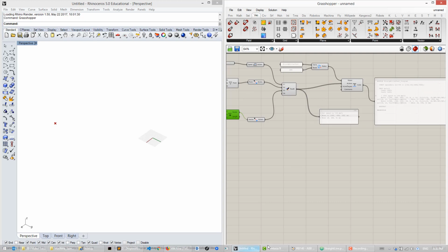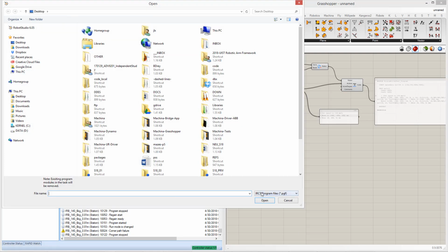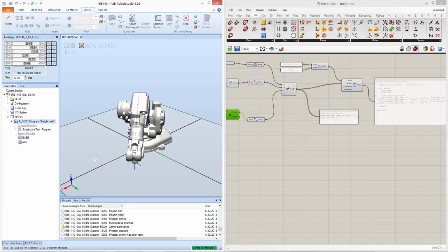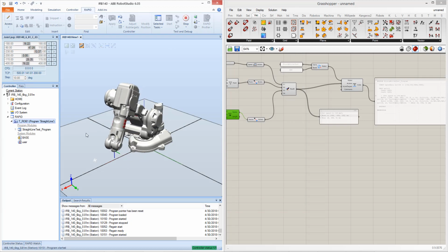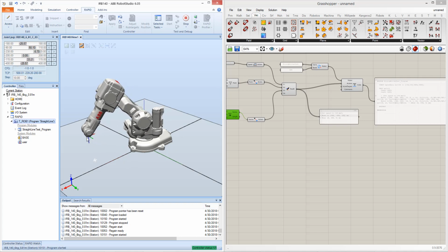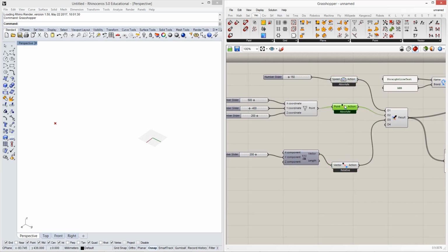If I run the compiled program like that, I'm going to load the program, I'm going to set PRG, and I'm going to look for a straight line. Let's see. I can go, and it's going to go to the first point, and then it's going to move 200 units in the y direction, and that's it. So that's the difference between absolute coordinates and relative actions. Absolute actions and relative actions.